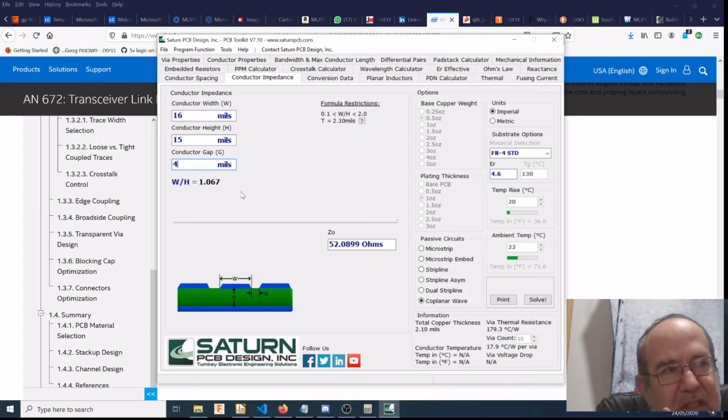The problem with this is that you have undercut, which means that when your PCB is etched, it's not a straight line. You don't etch straight, you etch with undercut. And it's actually the opposite way to how it's shown here. This is shown as wider; I personally think it'll be the other way. I think that you will have undercut.